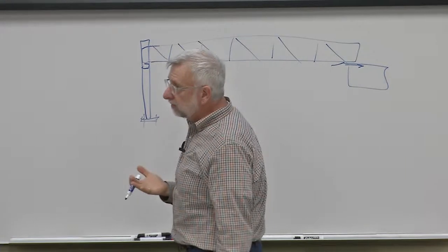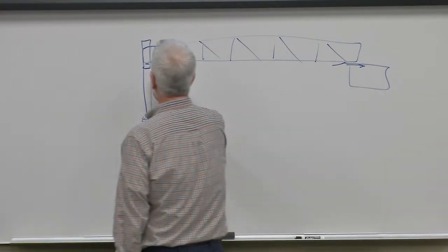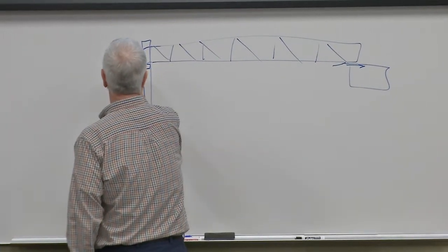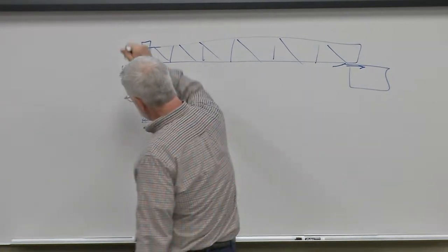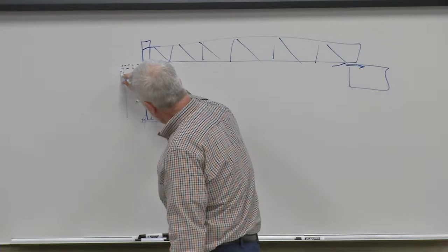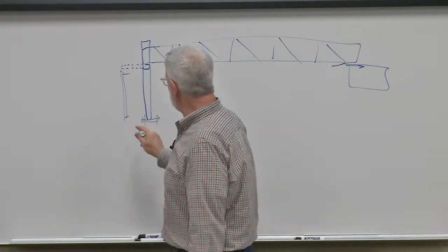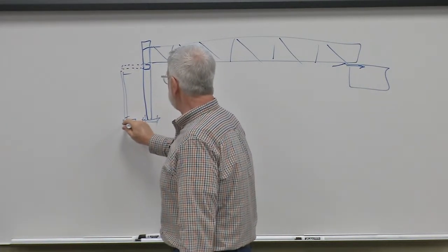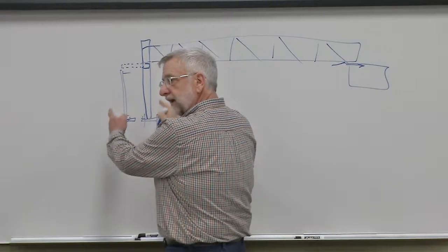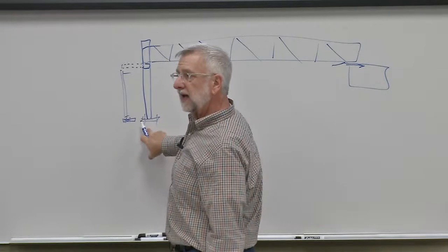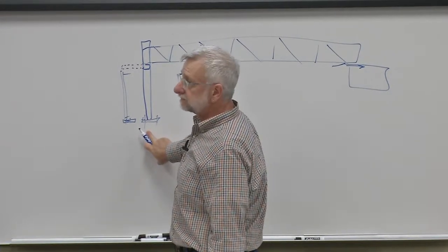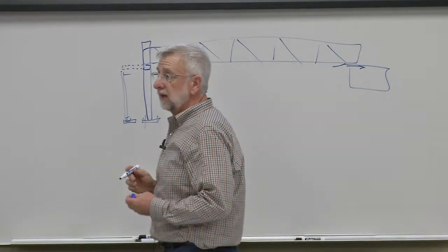Now, it probably won't collapse quickly, because over here, and this is not a part of the structural design, there's a platform right here and stairs going out this way, and this has got a support coming off of it as well. So in fact, we've got a little bit of frame action going here, but it's designed so that the bolts carry all the load. So yeah, if we lose a bolt, we're liable to lose the bridge.